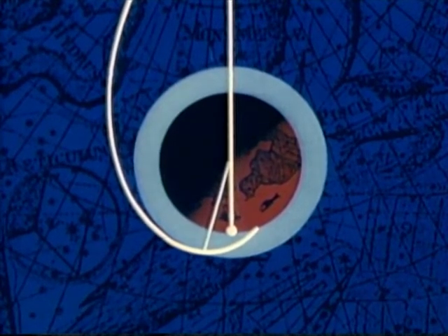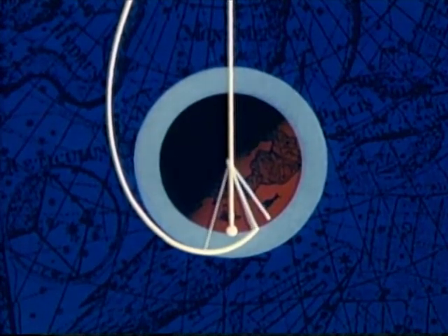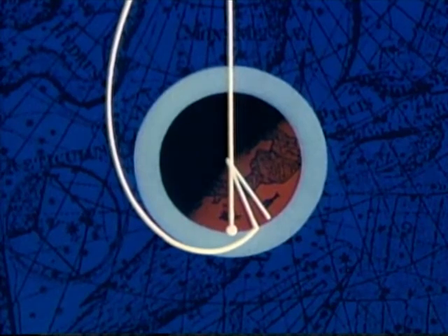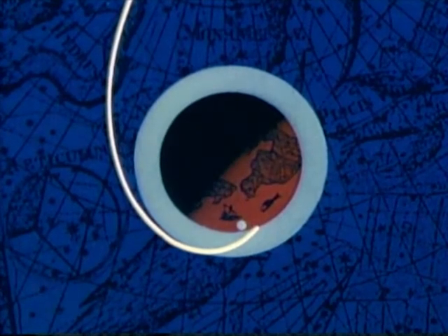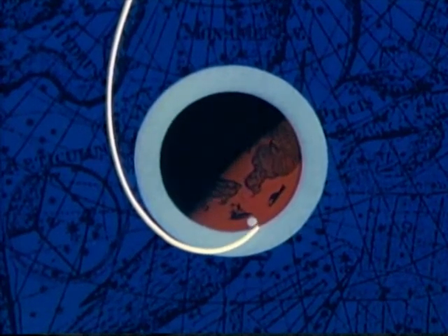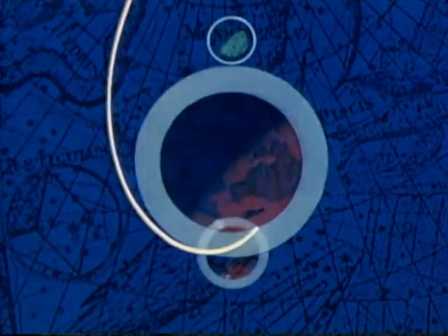The entry range limits of the spacecraft are also fixed so that landing occurs near the antipode. Therefore, the landing area is defined, and the target point can be selected within this area. The recovery forces are, of course, located on the surface of the Earth and rotating with it, while the trajectory is fixed. By selecting the proper trajectory, we can vary the transit time of the spacecraft up to 24 hours.